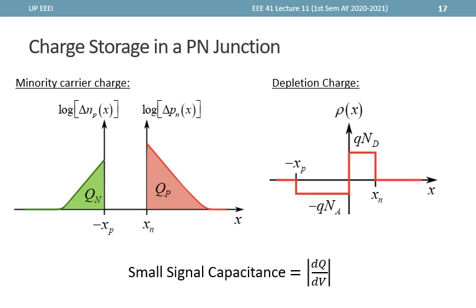Moving forward, we'll now discuss the small signal capacitance. However, this capacitance is unlike our usual capacitance, and instead we'll define the small signal capacitance based on the incremental amount of charge we get for every incremental voltage that we apply. So we actually get dq over dv, and not exactly q. Okay, we get the incremental q per incremental voltage.